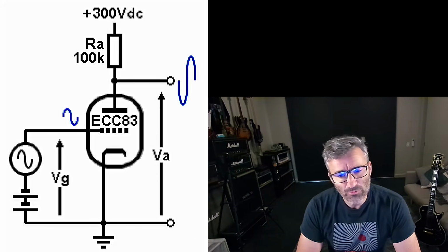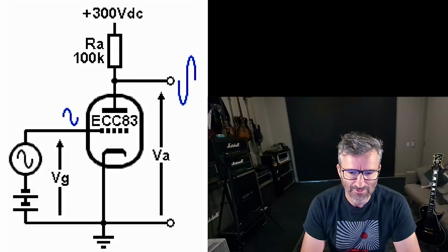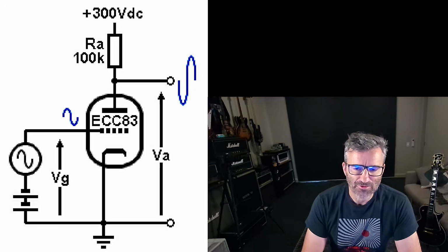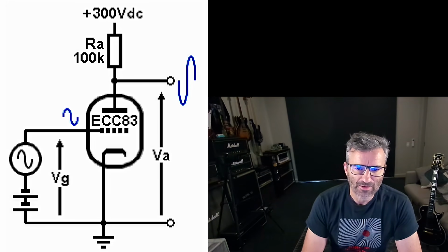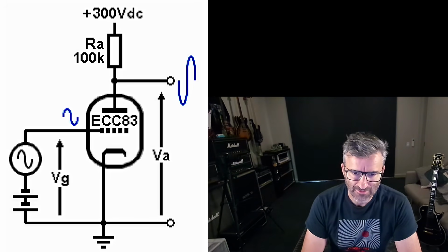So we should all know that in a power stage you have to bias. In a fixed bias amp, you have to adjust the bias of the power stage, an EL34 or 6L6, what have you. And a triode, 12AX7, or a preamp gain stage, is actually no different, right? It is a gain stage. It needs to be biased to give you optimum amplification. And you can adjust the bias of it to get different characteristics in that amplification.